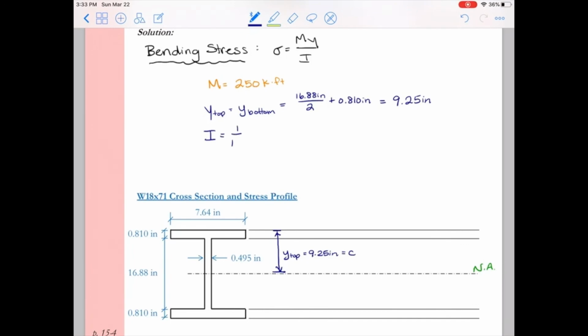But just in case you don't remember, for rectangular elements, the moment of inertia about the center of a rectangle is 1/12 b h cubed. And then we're going to add in the A d squared term. We have to do this, this is the parallel axis theorem, whenever those plates, those rectangles, don't match up to the overall center of gravity of our cross section.